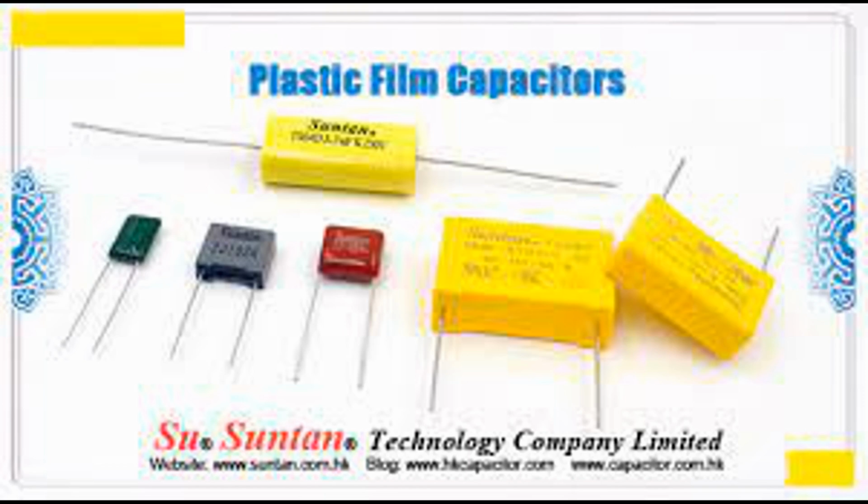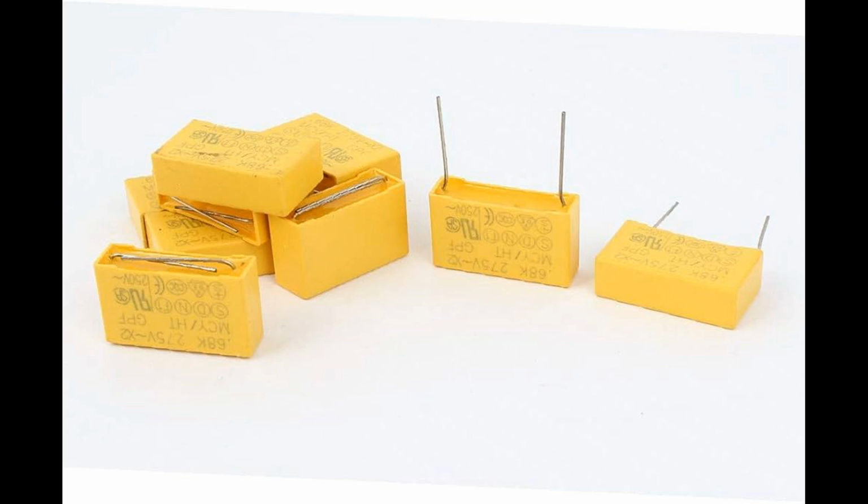5. Encapsulation or enclosure. The wound element is enclosed in a plastic or metal case for protection against environmental factors like moisture, dust, and mechanical stress. Some film capacitors are filled with resin or epoxy to enhance durability and increase insulation. 6. Additional features. Safety features. In certain applications, the capacitors include internal fuses or special self-healing properties.